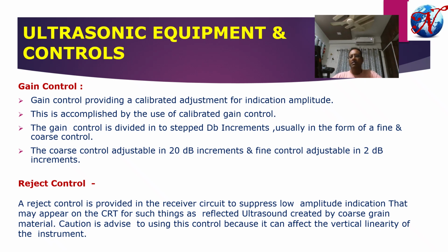Each and every ultrasonic machine has a reject control unit such that we can reject a specific percentage of the height of the reflected echo.